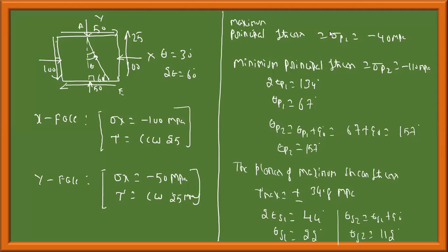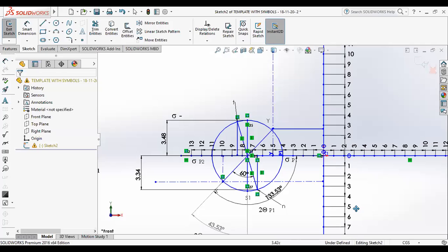Okay, I'll stop at this point. I'll send you the image of the graph sheet, the problem which I've solved on graph paper. You can have a glance at that. You should construct it graphically. Let me consolidate once again and tell you what you have to do. Keep these three points in mind. First, you mark x and y, okay? And wherever the circle meets, that is sigma p1 and sigma p2.